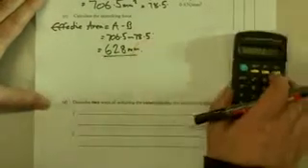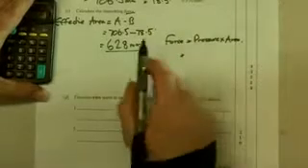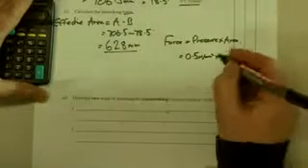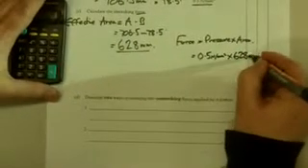Now we're only halfway there. We found the area. We now need to put it into the formula for finding out the force. Well, the force is equal to the pressure multiplied by the area. So pressure is given to us as 0.5 newtons per millimeter squared, times the effective area 628 millimeters squared.